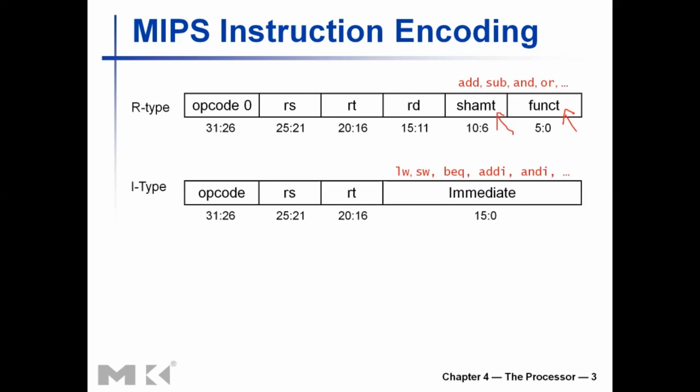So it depends on what instruction is being executed, but usually RT is used as the destination or the source register for either a load or store instruction. RS is treated as the base register where the base address is in, and the immediate operand will give you the offset. So what will happen in a load instruction, for example, is